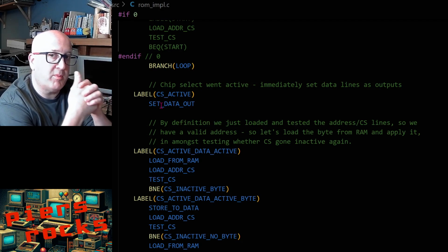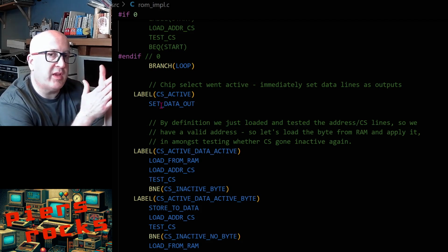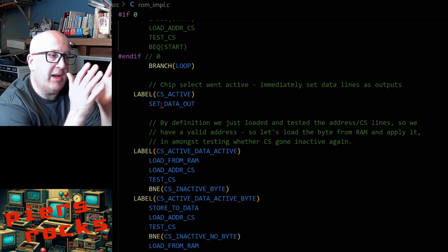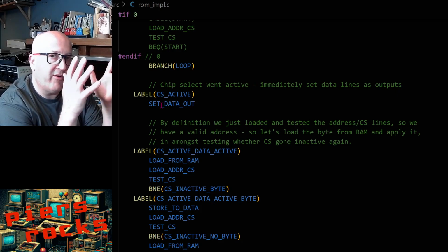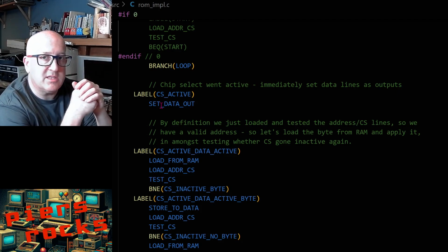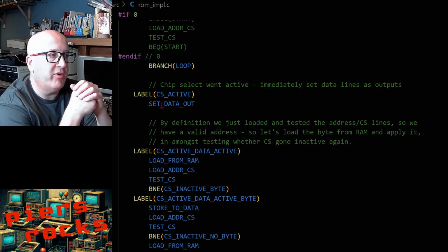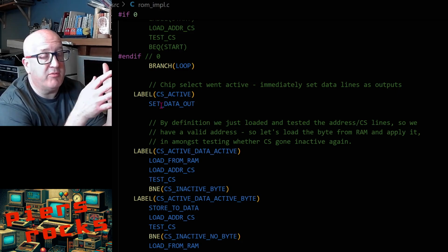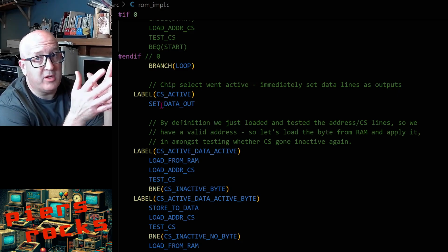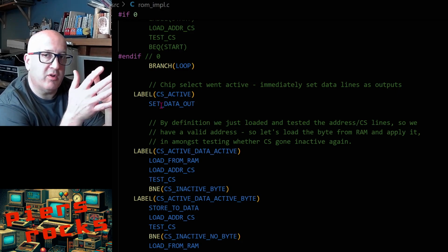I've been able to successfully replace ROM chips and the character ROM at that level. And on the C64, I forget the exact values, but for the character ROM, the STM has to be clocked at 98 megahertz to get a stable character output, at least on my PAL C64. I expect it will be slightly different on NTSC. That means that for at least my purposes, the F411 processor is good enough. That's got a max clock speed of 100. But you might want to go to a faster processor.